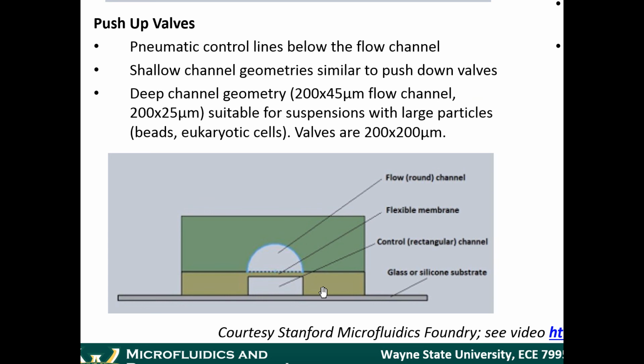Think about how the valve is going to move. Did it get more pressure on the button? More pressure? Not quite. Think about sealing. So it's like flush at the top? Exactly. If it's rounded, then when this membrane deforms, it's going to deform into more of a hemispherical shape, right? So it'll form a better seal. So in fact, it will be able to handle more pressure.